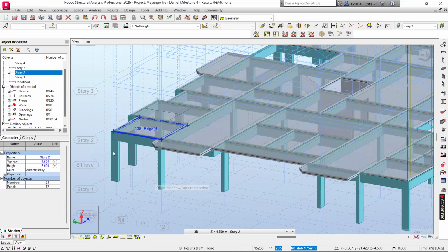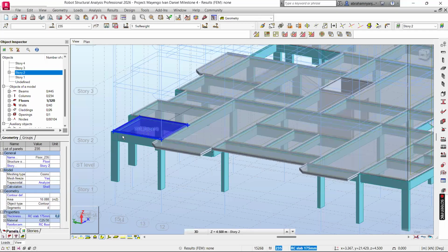The moment you introduce columns, you now have the circle and the triangle. The circle means the node, because you have introduced a column that has a node, and it has a member which is a triangle. So when I'm pressing this slab, I will place it at the grid intersection where I earlier positioned the column. That is basically the major check as you're pressing your slabs.